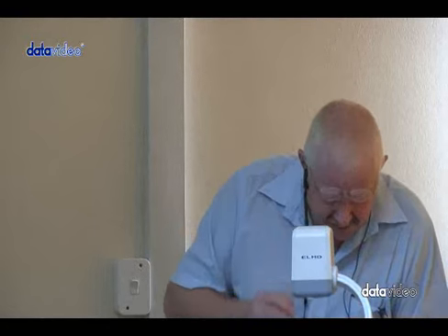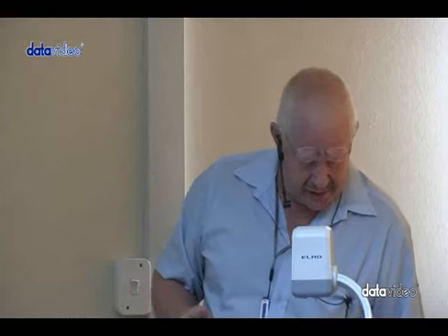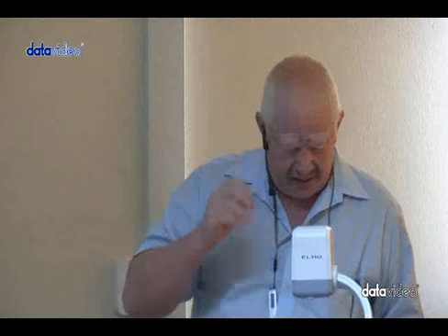Five r parameters commonly used for BJTs are given there in table 6.1. Now alpha and beta you are familiar with. You have done it under DC, but these are the AC quantities if you look at the lowercase subscripts. Alright, so I can see that alpha AC is still the ratio between collector current and emitter current. Beta AC is still just a ratio, no unit, between collector current and base current. The new ones that are introduced here, however, are the AC emitter resistance, the AC base resistance, and the AC collector resistance, indicated r'e, r'b, r'c.